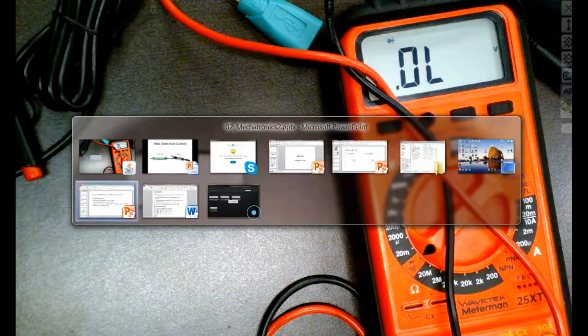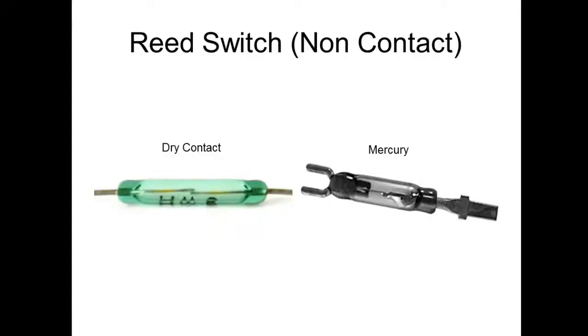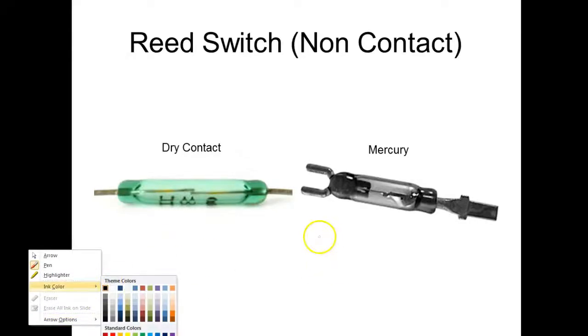So we have several of these on the manufacturing lines over there, to sense magnets. What they've done, and I told my night class this, is these guys are so popular now that pneumatic cylinders are usually made out of aluminum, and aluminum is a non-ferrous metal, so it won't impede the passing of a magnetic field. So on most of our pneumatic cylinders, you can get those.